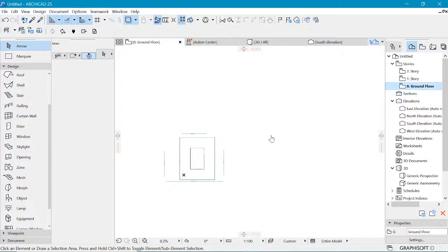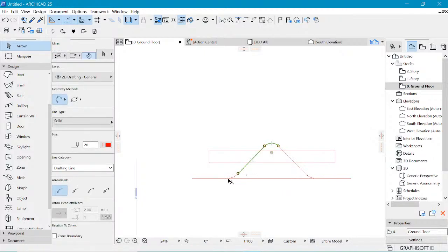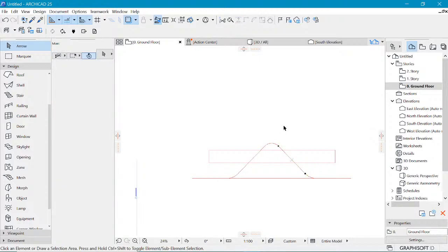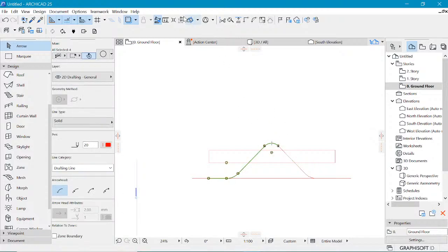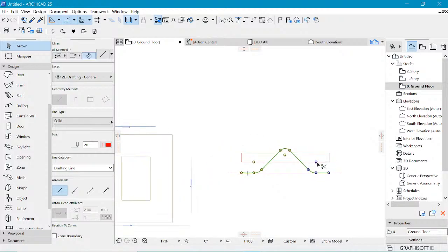And of course the reference was on the ground floor, so we have something like this. So I'm going to move it away from the rest of the things such that we are able to see what that is. Control E to suspend group. If something is grouped and now it's not, make sure that you unsuspend group. So right now the groups are suspended and I can only select one at a time. But if I unsuspend the grouping, it should automatically select grouped elements. Yeah. So let's move maybe a copy of it somewhere here.